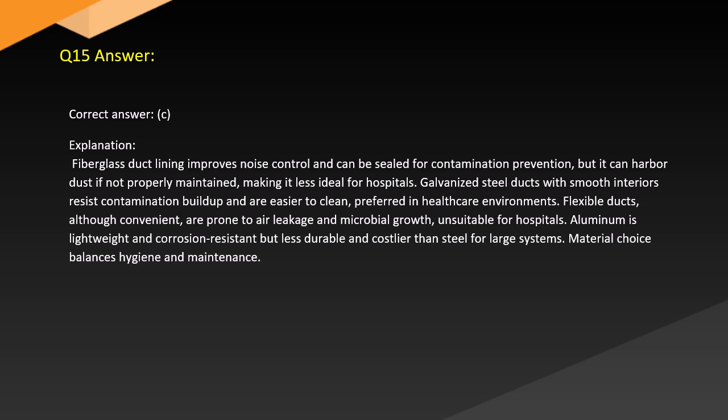Flexible ducts, although convenient, are prone to air leakage and microbial growth, unsuitable for hospitals. Aluminum is lightweight and corrosion resistant, but less durable and costlier than steel for large systems. Material choice balances hygiene and maintenance.